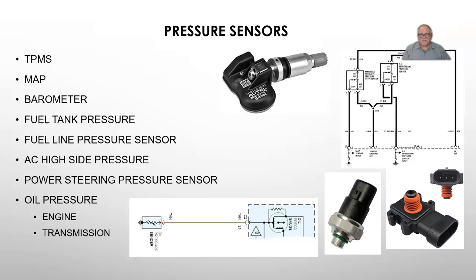What you have to be careful of on today's vehicles is that the manufacturers have switched over to using a high volume, low pressure pump on the engine. And what some of them are saying is that 4 psi or 7 psi is just fine for the engine. It will live no problem with pressure that low. If a customer brings their vehicle in talking about low oil pressure, you need to check the oil pressure, put a mechanical gauge on there, look at the spec, and make sure that there really is a problem before you try to diagnose it.